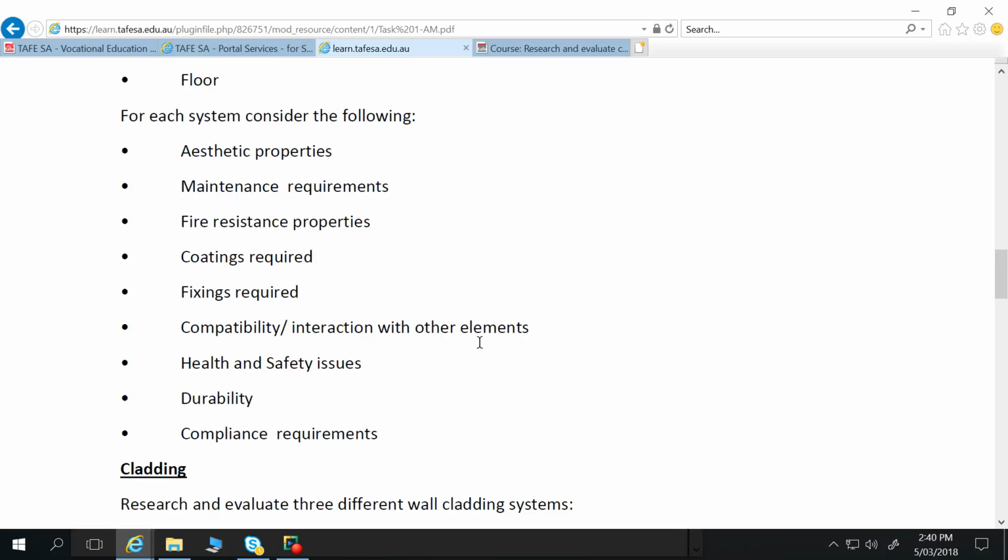I guess the important thing to look for in product literature is what they don't mention. They will want to tell you all the good stuff about it. So they'll say, blue board looks fantastic. Well, I guess that's a bit subjective there. The maintenance requirements are low. Unless your house is in a reactive site where you get gaps opening up between your blueboard sheets and cracking in your render there. So look for what they don't mention and think about what is not mentioned in the product literature, because the product literature wants to sell the products to people.